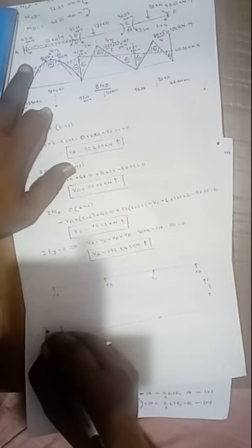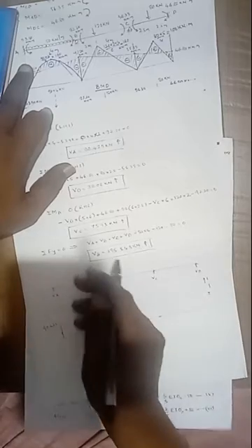Here, start from one end. As per your sign convention, left upward is positive. Here, if you consider a section in between A and B, at A the shear force is, here I will draw a reference line or datum line. Here Va is, just now we have calculated, 90.425, that is upward. Only to the left side there is only one reaction.